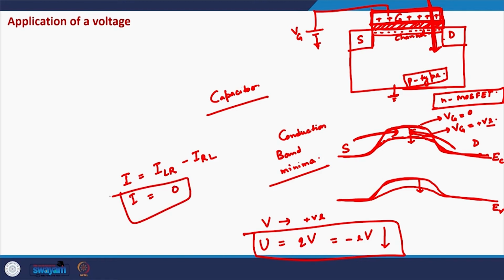because we are assuming that the gate terminal is uniformly put across the channel. So, if there is any positive voltage on the gate terminal, it will uniformly lower the barrier in the channel. So, it will allow electrons from both sides to cross the barrier with equal chances.